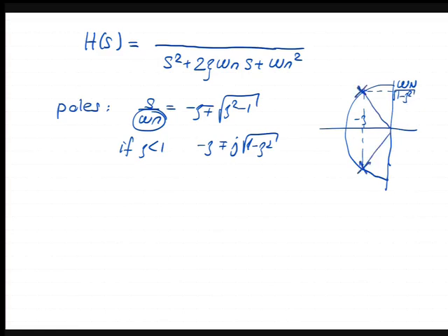Okay? So why is this parameterization useful? Because the omega n parameter tells me how far away those poles are from the origin. Right? And zeta tells me how close to being real they are, right? So zeta is the real part. As zeta comes close to 1, that means these poles have moved closer to here, right? As zeta comes close to 0, it means they are close to here, okay? In fact, you can define this angle here to be theta.